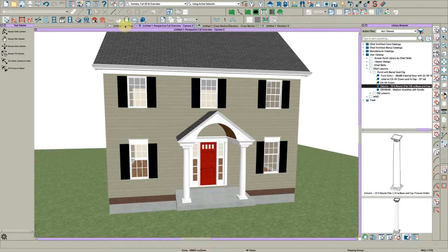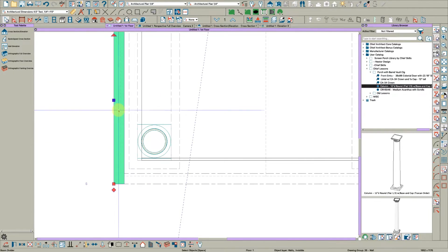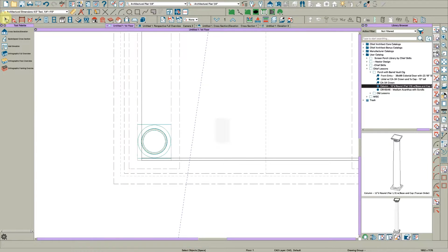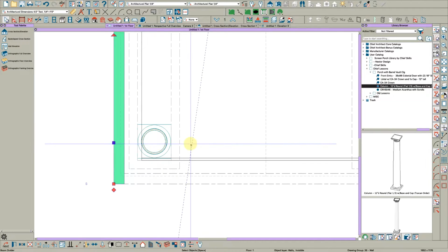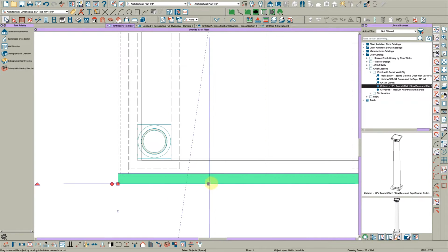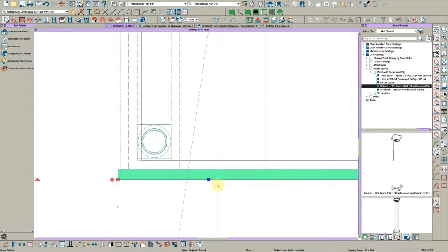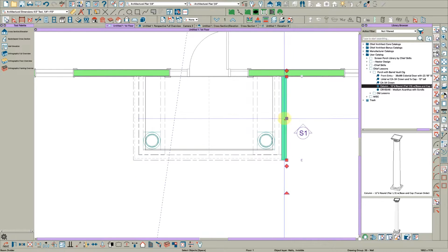but you see how you can do that. You can just go here to your floor plan, click on the wall, and I have my grid snap set to 1 inch. So each time I move it with my arrow, it moves at 1 inch. So let's just move it 2. How about this one 2? And then this one 2.